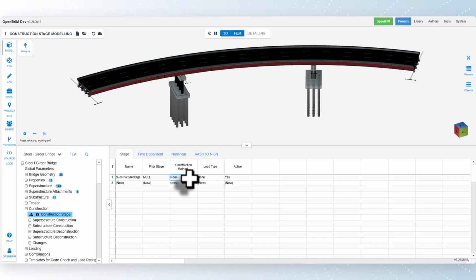For example, during the construction of girders and the application of deck load, girder nodes experience displacement while deck nodes do not. In construction site scenarios, the deck formwork also undergoes deflection due to girder displacement. To address this, the node coordinates of the deck must be adjusted based on girder displacements. The equal parameter modifies the initial node coordinates of the deck shell elements by applying the top node displacements of the girder to the closest nodes.